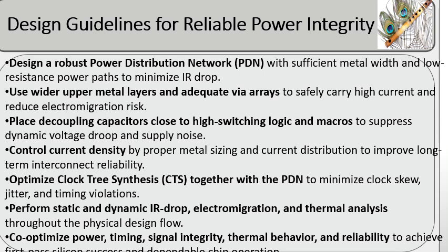Power integrity and clock tree synthesis should always be optimized together to minimize skew, jitter, and timing violations. Finally, continuous IR drop, electromigration, and thermal analysis throughout physical design ensures reliable, high-performance ASICs with successful first-pass silicon.